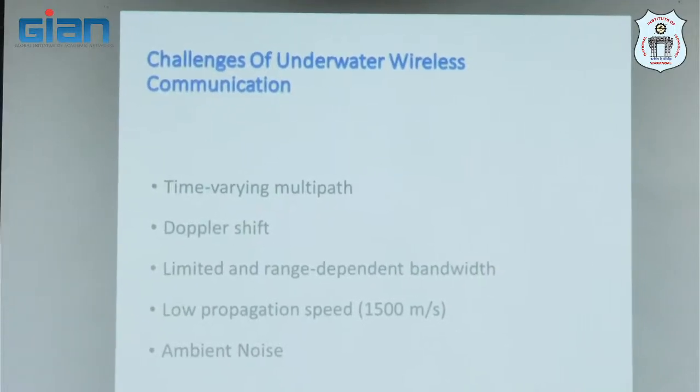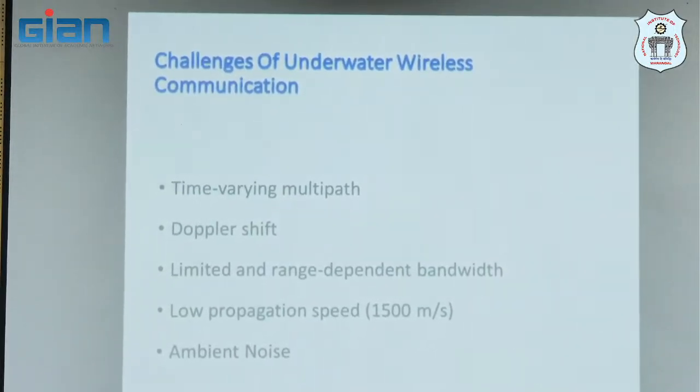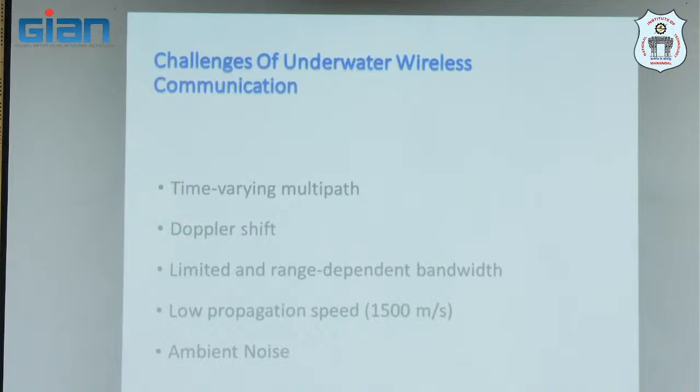So, underwater wireless communication challenges. The underwater channel is time-varying multipath in nature, and it has Doppler shift because the channel itself is dynamic, and the vessels or submersibles in the ocean are also moving. The channel has limited and range-dependent bandwidth. If we want to communicate over a very long distance, we have to go for low frequencies, which means very limited bandwidth availability, so we will be able to communicate only a small number of bits.